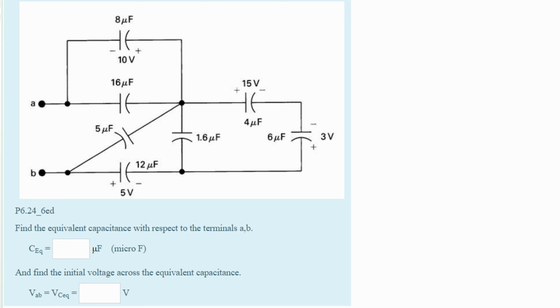Before we do any of this, we should write out what a normal capacitor looks like. We have one end like this, our line, then we kind of have this pipe, and then a parenthesis looking part, a line, and then our other node right here. Now this is what a normal capacitor looks like, because normally current is flowing in this direction, and then normally our voltage is going in this direction. Remember, voltage drop is from the positive to the negative, or the voltage goes into the positive and out of the negative. As long as our current and our voltage are in the same direction, that means we will have a positive. If our current is in a different direction, it'll be a negative.